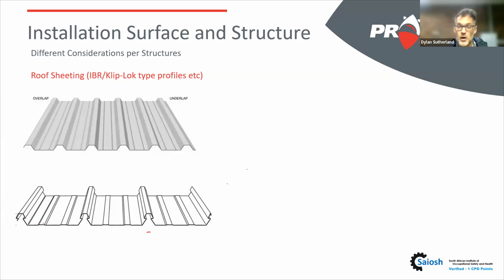The other side is polycarbonate sheeting, so the see-through light sheeting. That, guys, in fall protection, most incidents are happening off of roofs, and of those, I would bet 90 to 95% are happening through polycarb sheeting. It's an extremely dangerous space to play in, because that sheeting cannot withstand a person standing on it. It's not designed for that. It's only designed to allow light through into the warehouse or whatever it's guarding.